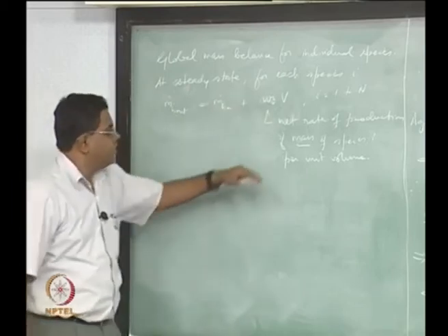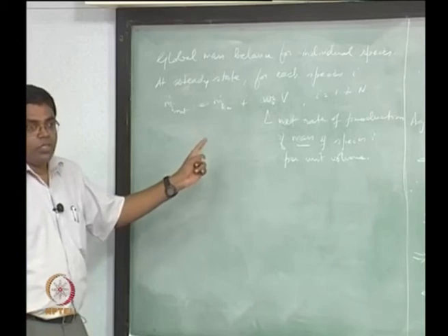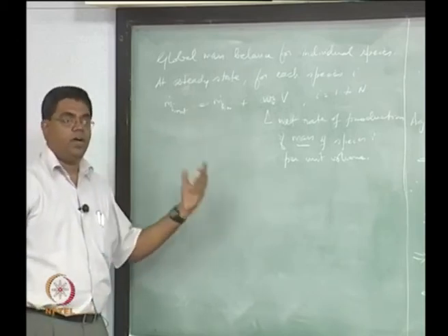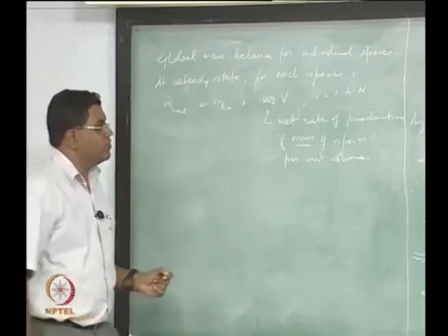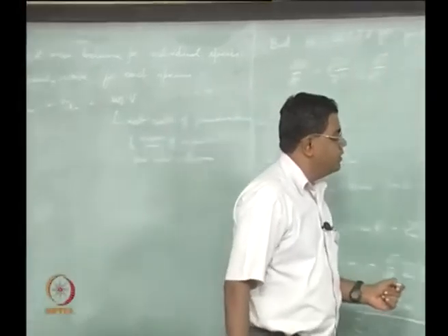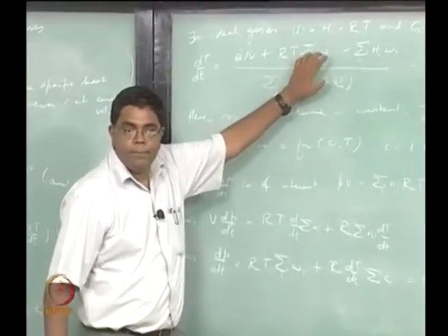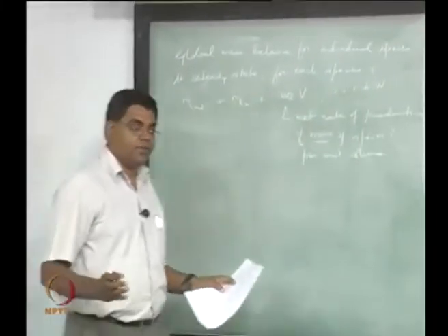Okay, and this is a mass basis, and this is what I was trying to point out. If you now get a sigma Wi, you should look for it to be 0 because mass is neither created or destroyed totally. Okay, but so long as you have a sigma omega I, that's alright, because number of moles is not necessarily conserved.